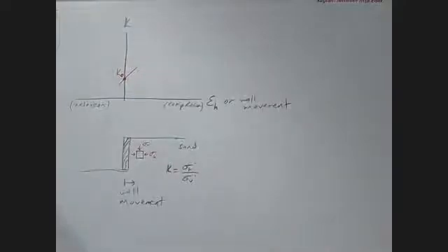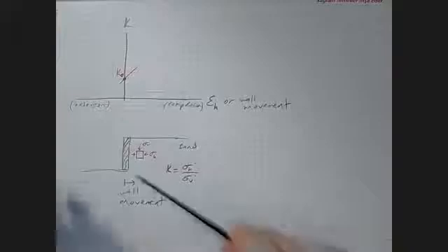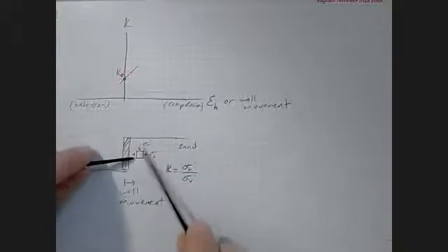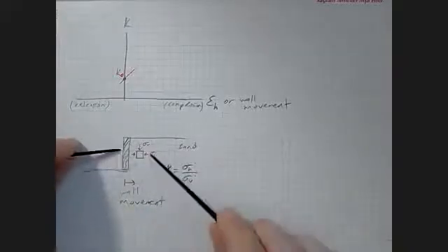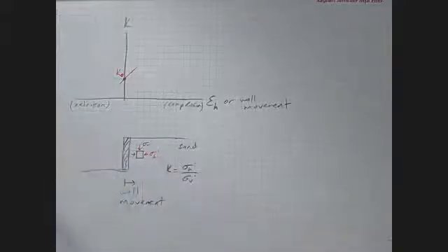But what happens afterwards? Now, I just said we are moving the wall so the soil is able to flow, or we are moving the wall into the soil and we are compressing the soil. So these don't sound like reasonable amounts of deformations. These sound like we are failing the soil. So actually, let's consider it from that light.